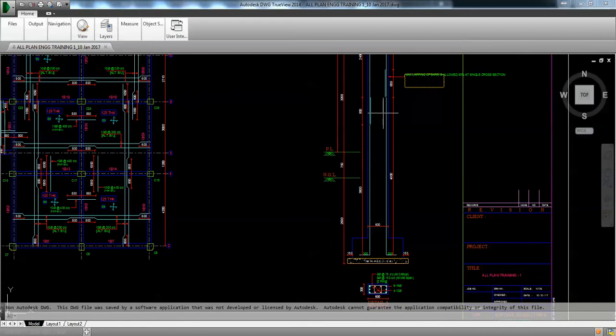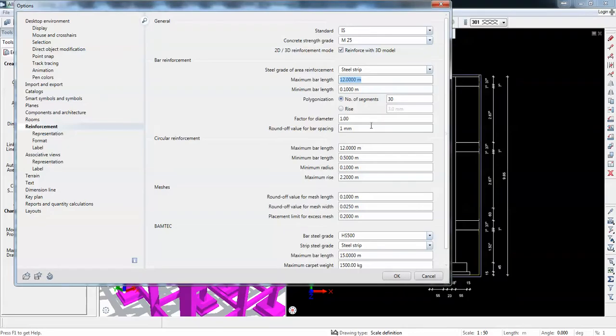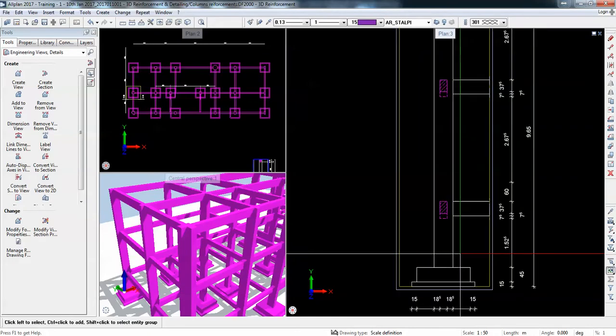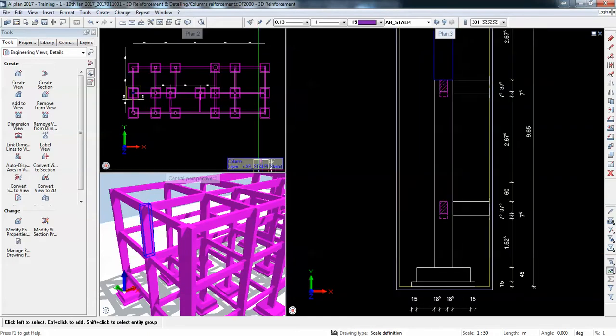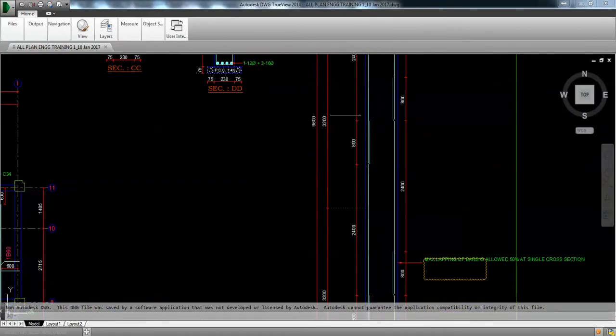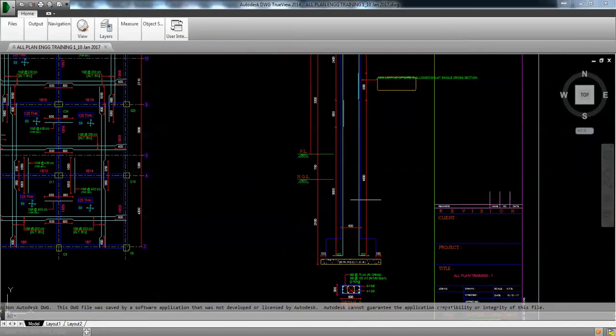Actually, I will input the biggest rebar you have, which will be 300 plus this, 4,600 millimeters. So I'll input this maximum length of the rebar. 4.9 will be the maximum for the beginning, because I need the program to have the maximum reinforcement exceeded in order to ask me how to create these segments and how much to do the overlapping. So this is the trick I'm using now.